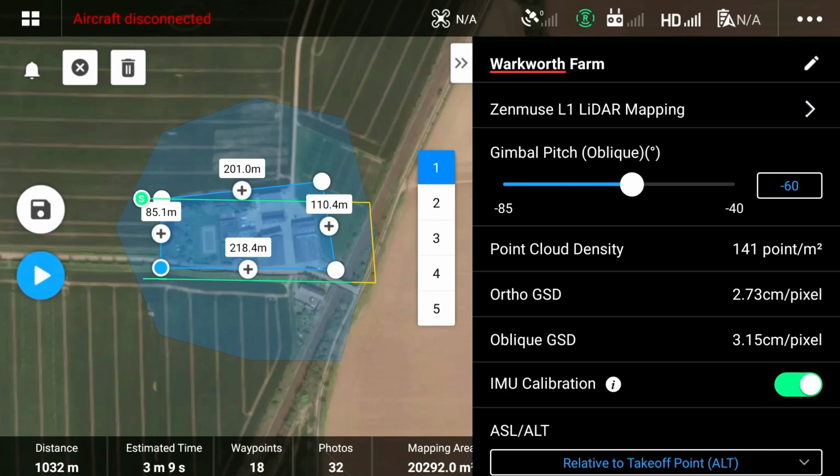At this point, it is worth noting that you can select or deselect any of the 5 sub-missions. Therefore, if you only need oblique data for angles north and south of your dataset, then you do not need to collect the east and west images. This is especially useful in examples such as quarries that may have one severe or linear cliff face.